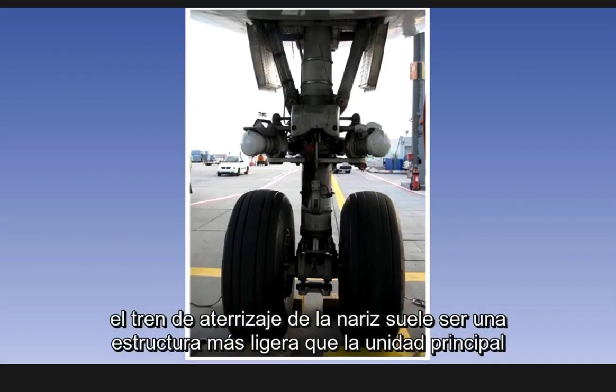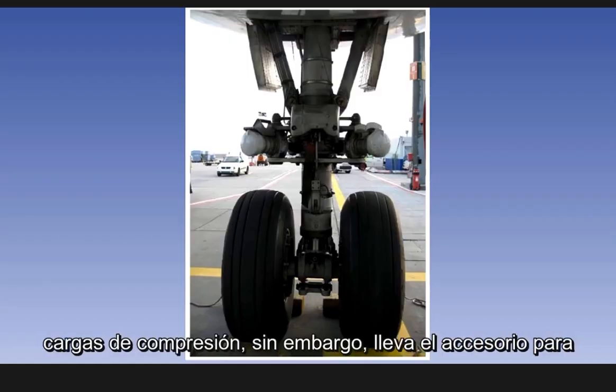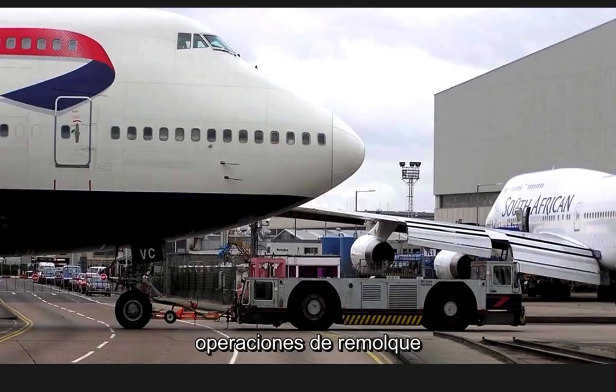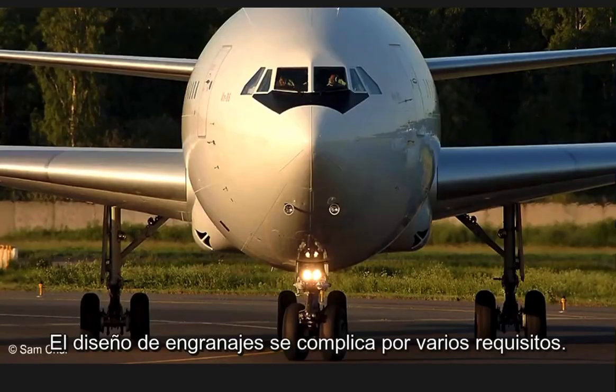The nose undercarriage is usually a lighter structure than the main unit, since it carries less weight and is usually subject only to direct compression loads. It does, however, carry the attachment for the towing equipment, and so must withstand the shear loads associated with towing operations. Nose gear design is complicated by several requirements.